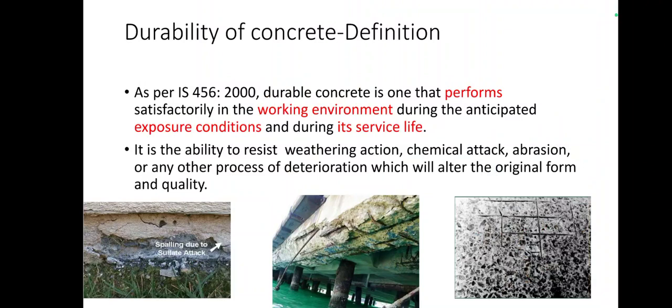So how the concrete performs in its service life when it is exposed to various environmental conditions, that is the definition of durability. In simpler terms, it is how a concrete resists weathering action, chemical attack, abrasion and other processes of deterioration without altering its original form and quality. That is very important.